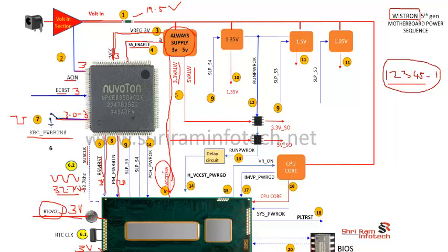So once the CPU gets this step number 8, the PM power button, the CPU sends out 2 signals, called SLP underscore S4 and SLP underscore S3. SLP means sleep. In a laptop there are 3-4 power states, let's call them S5 state, S4 state, S3 state, and S0 state. S5 state means the standby voltage, S4 state means the RAM voltage is on, S3 state means the whole system is on, and S0 state means all powers are on.